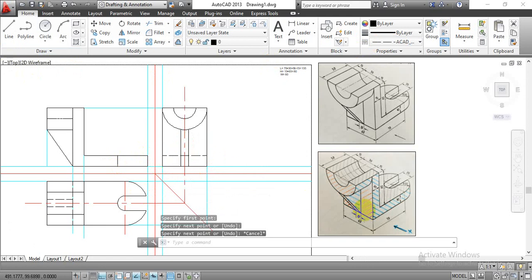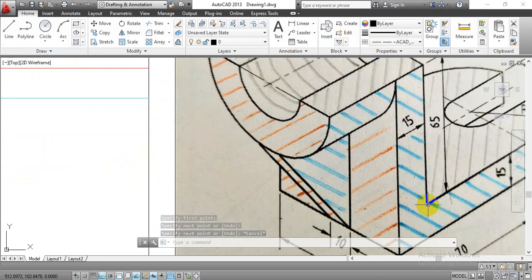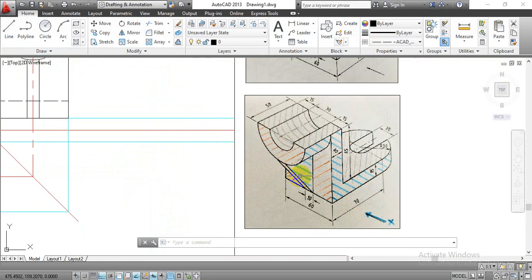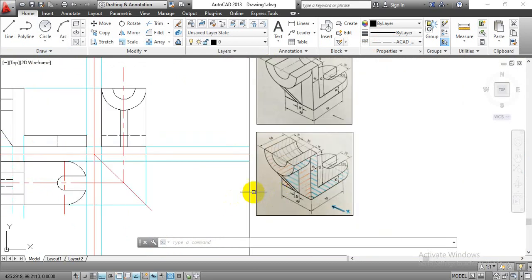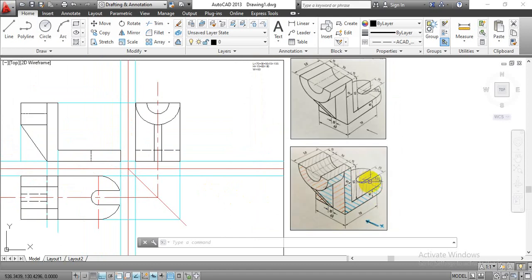Now this dotted line is for this corner point. So that corner point we have for the throughout width equal to 60 mm over here. That is invisible to the observer while looking for the side view. And we confirm that this semicircular slot is for that much height only. So we are going to project all those projections over here, and that we are going to use to have a vertical dotted line over there.